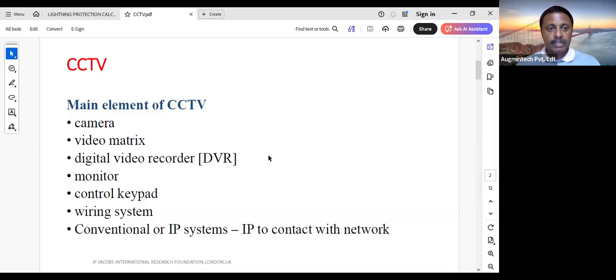So here the final voltage required is 12 volt DC. That's what is required. It might be any other system also, like an access control system for access control panels, or for door controls, where we use electronic sensors, etc. For each and everything, we need a 12 volt DC supply. From AC, it should be converted to DC, so we need an SMPS actually, right?